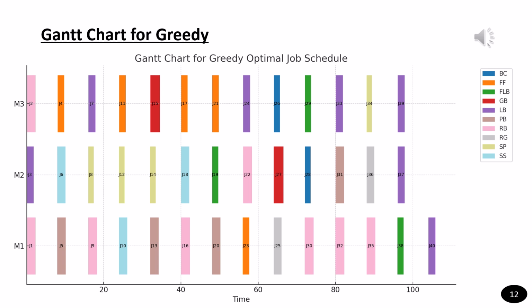This Gantt chart represents the outcome of the greedy algorithm. Each job is slotted into the earliest available machine, but only after evaluating release time and setup time from the previous mold. As we can see, this approach results in minimal machine idle times and efficient use of molds. It aligns with shift-based release, making it a more practical solution for industries with such constraints. The smoother mold changeovers here contributed to the lower Cmax value.